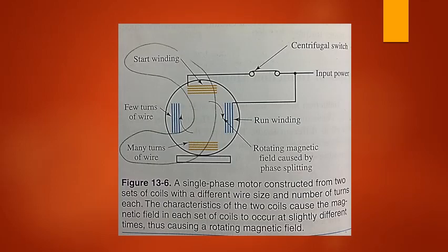When wire is shaped into coils, the coil creates a certain amount of inductive reactance. Inductive reactance means that there is a force that opposes the current flowing through the coil. The amount of opposing force depends on the number of turns of wire in the coil. More turns of wire produce more inductive reactance. The induction causes the current flowing in the coil to slightly lag the applied voltage.